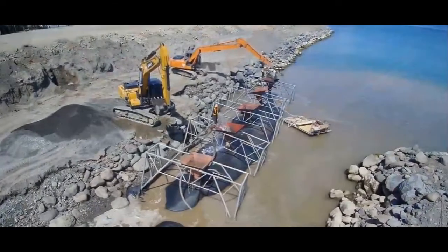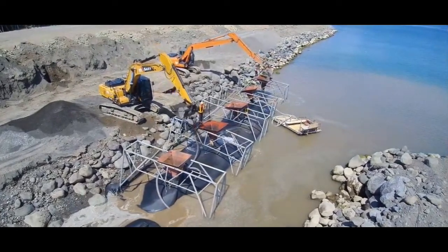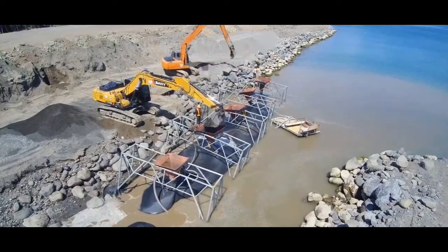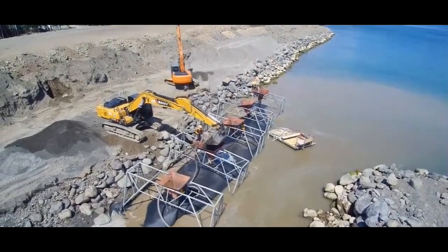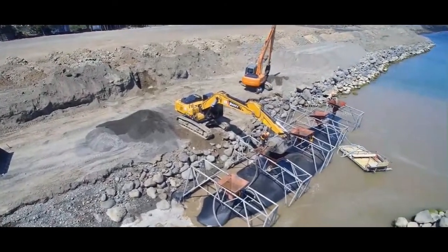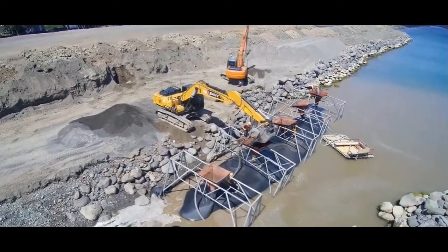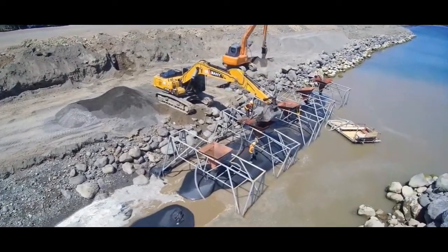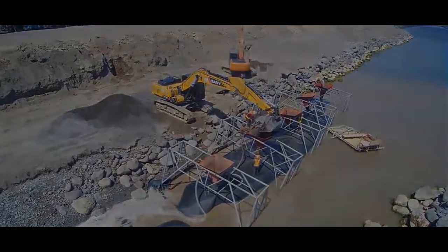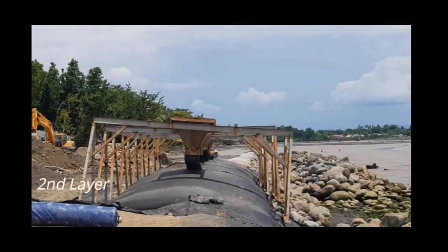After that, around 10 to 15% solid slurry is transferred through the piping system, with constant adding of sand and water supply rate. In this piping system, there is a mechanical pinch valve which is used to control the flow at each fill port. Dynamic adjustment is required for the pump speed, slurry storage percentage, and number of fill ports throughout the project development. This is because the piping system changes in terms of pipe length or structural combination as the project carries out from north to south.